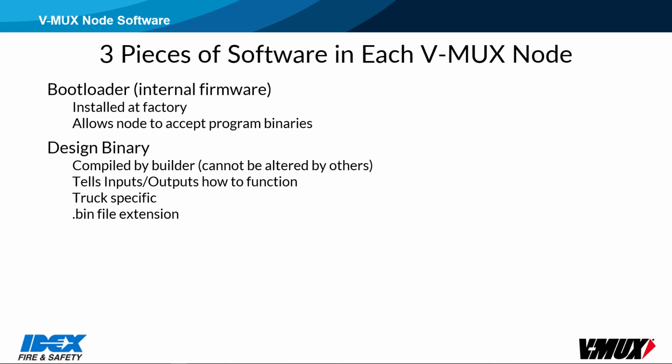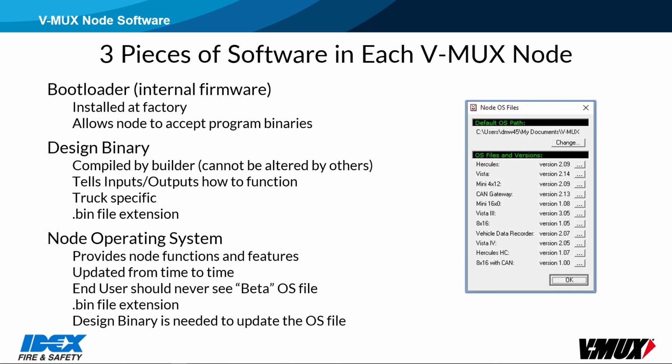Design binaries are truck-specific. The node operating system or OS file provides functions and features of the node. These files get updated from time to time. Generally, there is no need to reload nodes every time a new OS file is released. In order to update the OS in a node, you must also load the design binary file. It is possible to reload the design file without updating the OS, but the V-MUX downloader program will not work unless the OS files are installed on the computer.